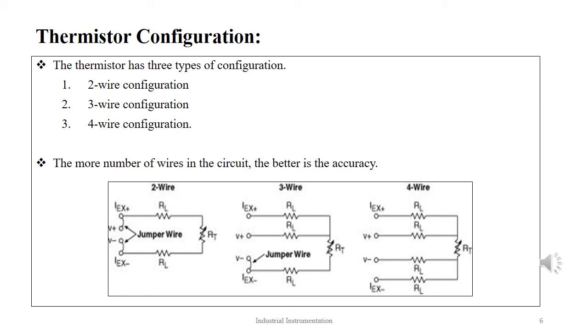The 3-wire and 4-wire configurations lead to a high impedance path along the measurement device and thus effectively attenuates error caused by the lead wire resistance. Thus, they give more accurate results than the normal two-wire configuration.